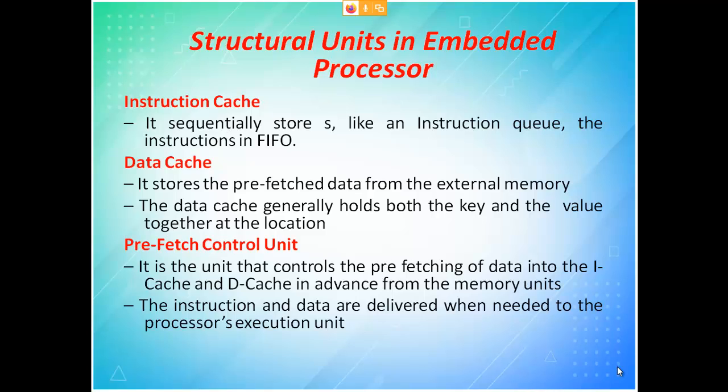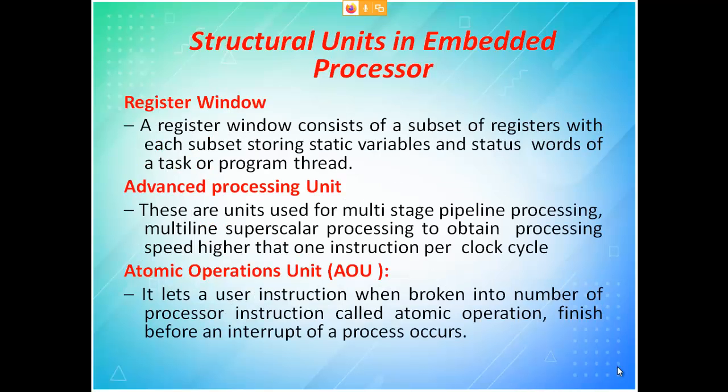Then the prefetch control unit. The prefetch control unit is the unit that controls prefetching of data. See, when starting, only one instruction came in, that was executed and some work was done. Whereas when you go for a higher level, we said we will put a pipeline. So when you put a pipeline, you should have a prefetch control unit also, so that you have the next one ready.